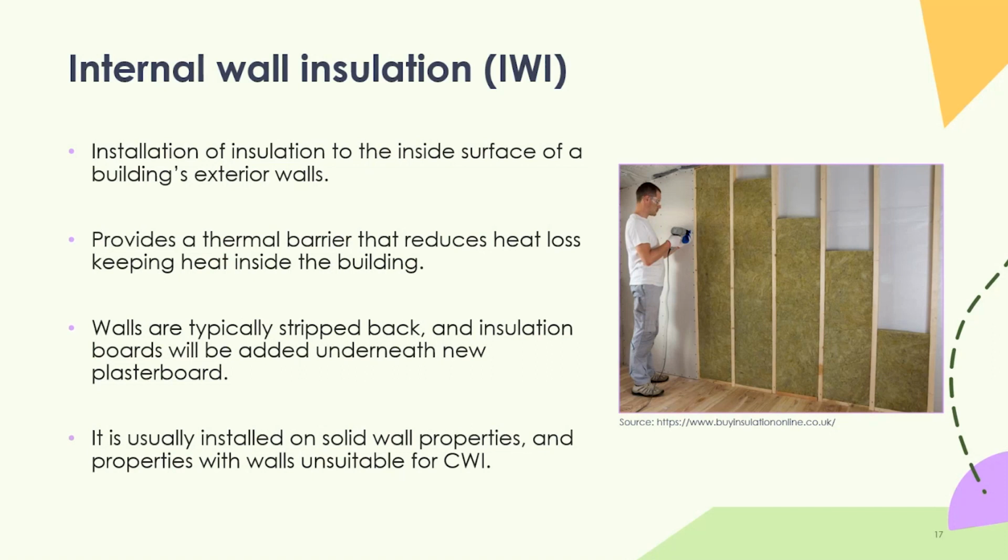And what we want to really avoid when you're introducing layers of insulation on top of these type of walls is to trap moisture in the wall. You basically need to avoid doing that. So you need to have what are called thermally open materials for solid walls, whereby you're allowing any moisture which might get into the wall to freely migrate out again. So that's something that the retrofit designer will be looking at carefully in terms of specifying this measure.